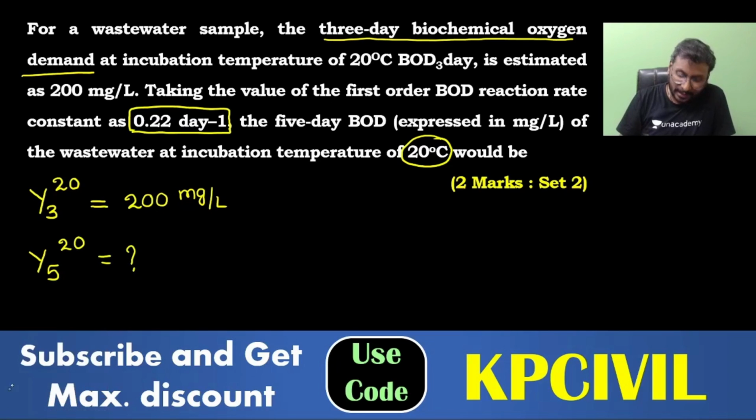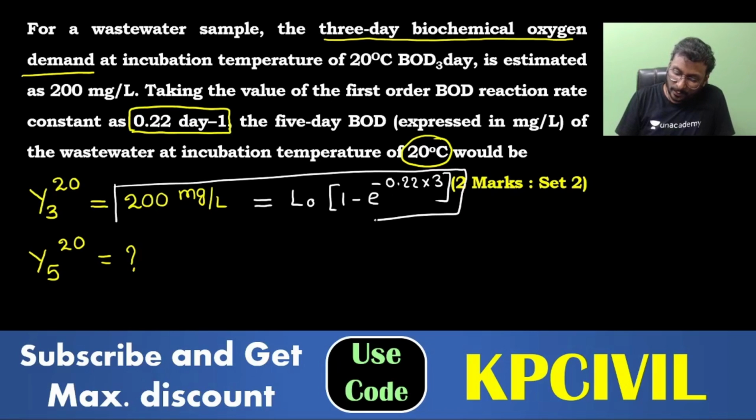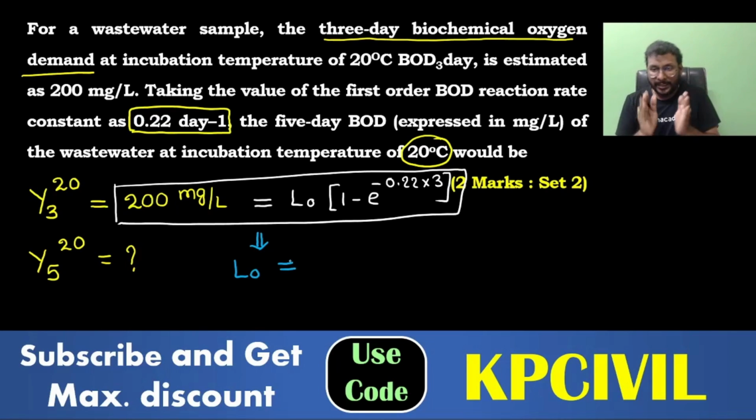Simple, you can calculate. Y3, 200 mg per liter, is equal to L0 into 1 minus e power minus 0.22 into 3. Using this, you solve for L0: L0 equals 200 divided by 1 minus e power minus 0.22 into 3.